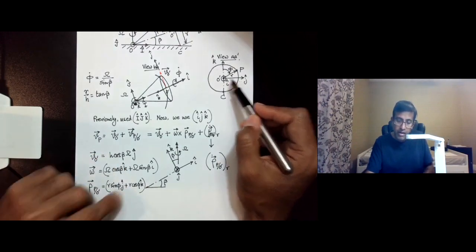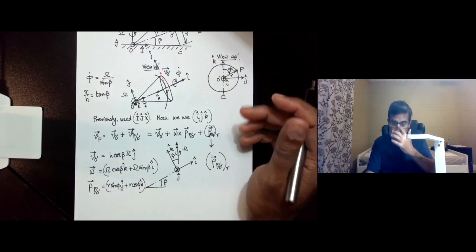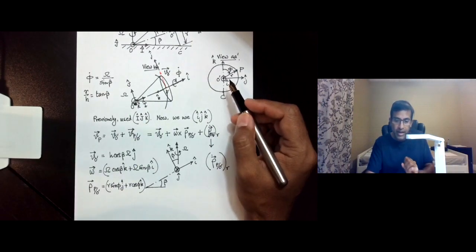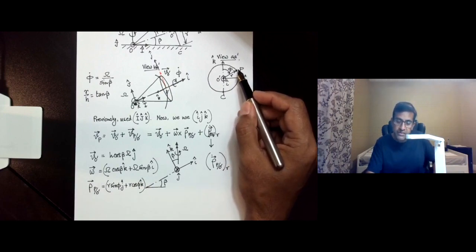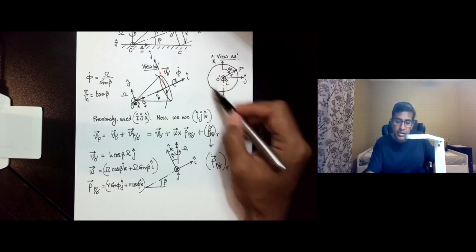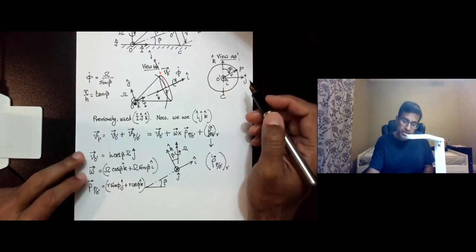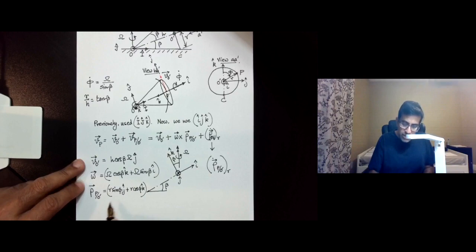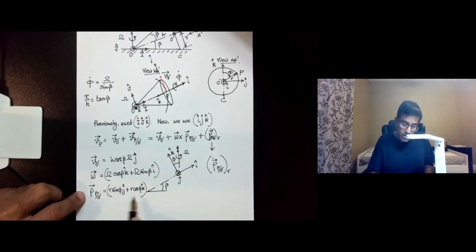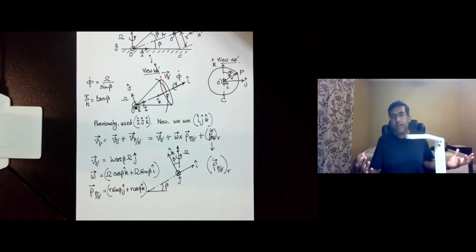So if you were I, j and k, and if you had sensors along I, j and k, and you were viewing the point P, then all you would perceive is the circular motion of this P due to the spinning of the cone about its axis of symmetry. So in order to find that out, we differentiate this position, but when we differentiate this position, we don't differentiate j and k. If we differentiated j and k, then that would be the net velocity of the point P.